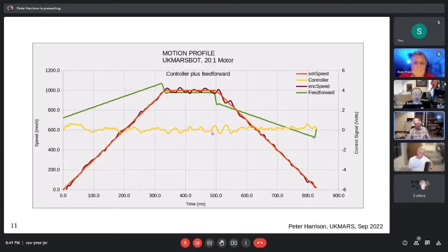Here, where it starts going up and down, the controller starts to worry a bit more to get things on track. And here, there is a slight positive average voltage out of the controller, and again, only about 200 millivolts, because the green line, the feed forward alone, is braking too hard. It's actually using the same constants as it does during acceleration, but braking is always easier than acceleration, because it's friction and all sorts of stuff, and so it didn't have to work that hard. But not to worry, we have a controller just to make up that little gap.